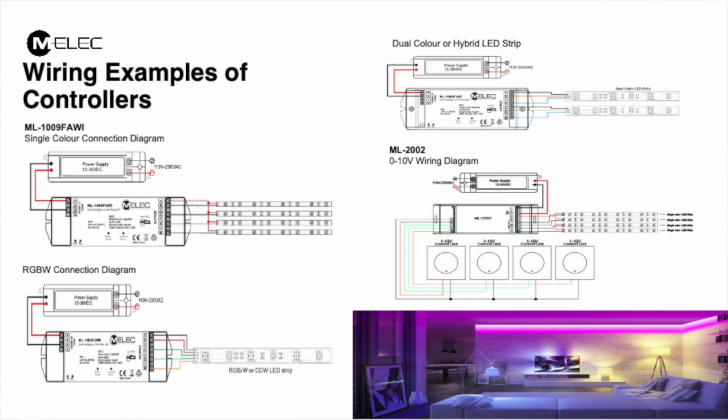basically the wiring of all of those is very, very similar on the output side. Even on the input side, you've still got a power supply coming in. That's all the same. The difference on a DALI is you will have a DALI bus coming to it. That is realistically the only difference.